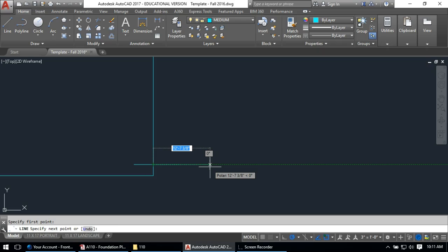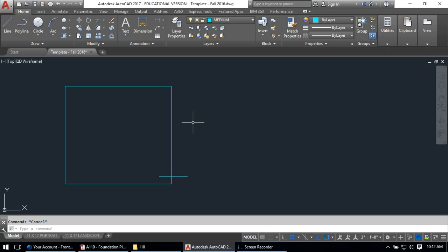Actually, that dimension has question marks up at the top. Oh, I guess they're giving the internal dimension, so I can draw that differently then. Sorry, this is the first time I'm drawing this floor plan too, and as you're going through these things, you might not get it right the first time. Actually, there's question marks on the inside as well. That is interesting. Well, let me think about this. I'm going to pause the video for a second and think about these missing dimensions. Okay, not a problem. I see that they have 21'4" as the internal dimension for this second room. So I'm going to offset 21'4".